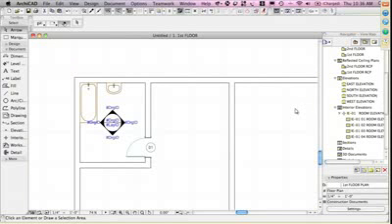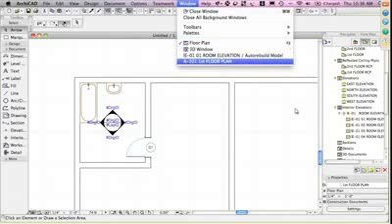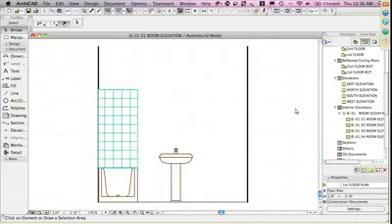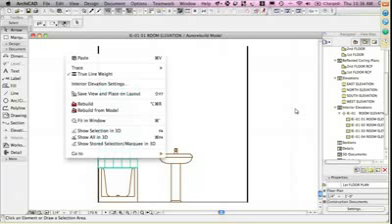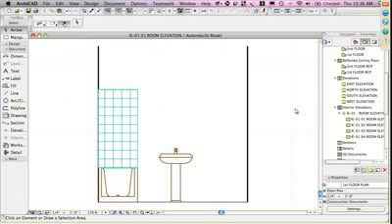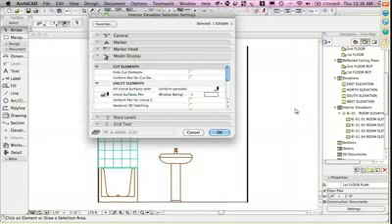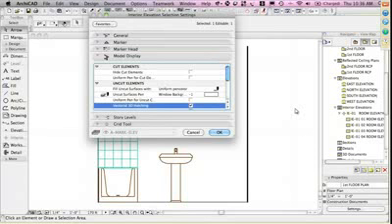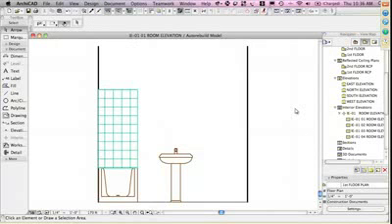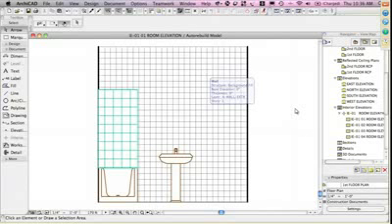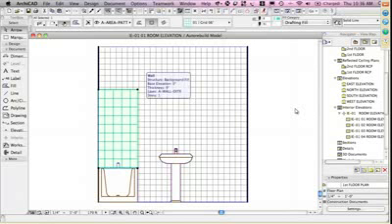Let's just go back to that elevation to look at that, and we'll see the elevation doesn't show that, and that's because of the settings. If I right-click in empty space, I can look at interior elevation settings. The settings for model display do not have vectorial 3D hatching turned on. So I'm going to turn that on, say OK, and now you can see the wall as a whole has a hatch, and this thing that I was creating manually, of course, is in one place.